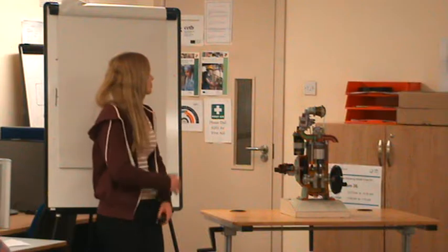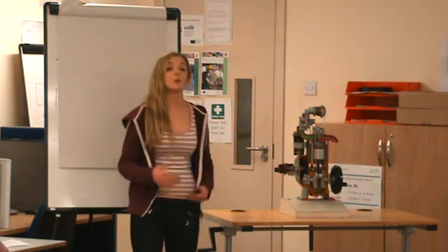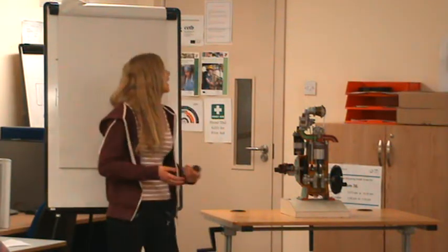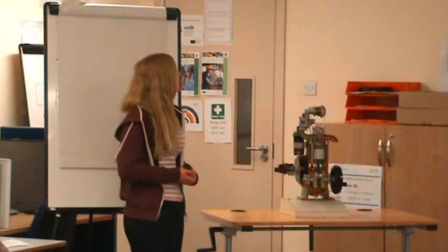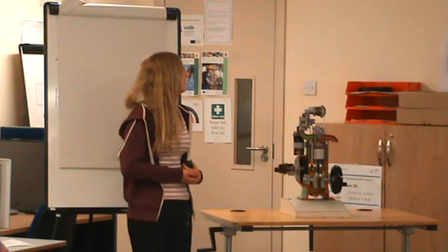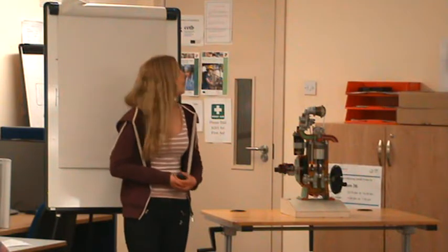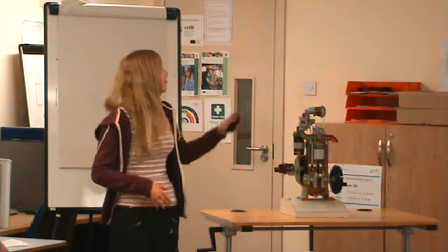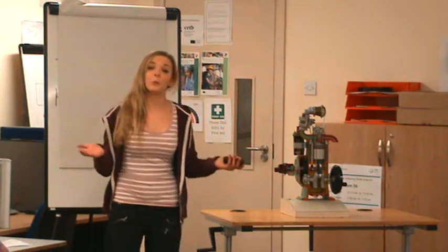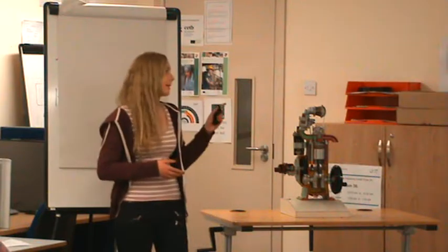So next we have our compression stroke. During the compression stroke, both the intake and the exhaust valves are closed while the piston is rising. So your piston is travelling upwards, and the face of the piston and the face of the valve seal the cylinder so that pressure inside the cylinder will rise. If you can imagine, like I was saying with the bottle, if one of those valves were open, you're not going to be able to build any pressure, it's all going to escape out the valve, so the valves always have to be seated closed.